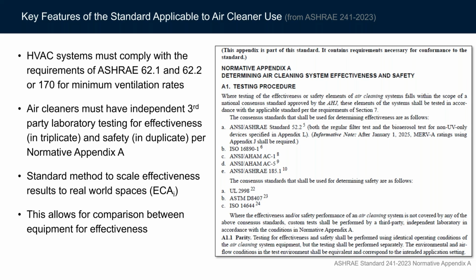And on the right, I'm giving you a screenshot of the normative Appendix A that they point to there in that bullet. And notice there are all these different requirements and testing procedures. Again, I'll go into some of these in some detail, but what's very critical as an engineer, and what I ask my engineers to do, is at the very least, look at the safety standard there and add that to your specification when you design for electronic air cleaners. And I'll point out what it's encompassing as far as which products or technologies, but there is now the safety standard that should be included.